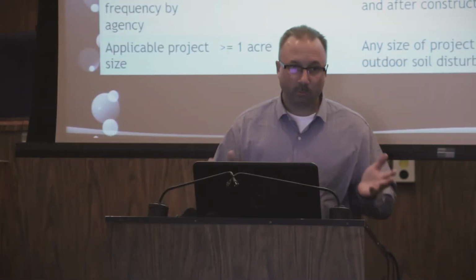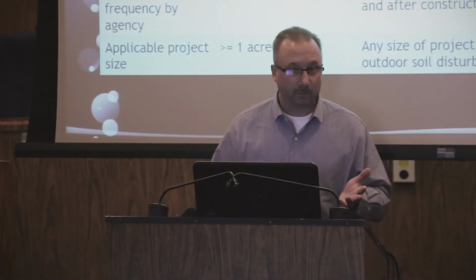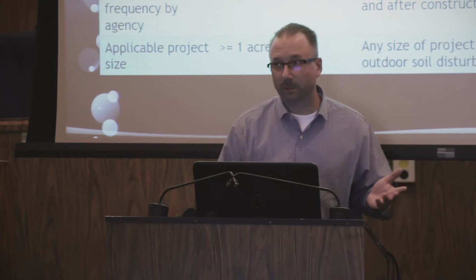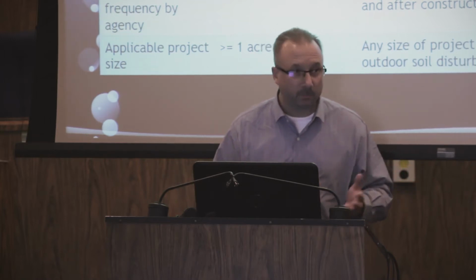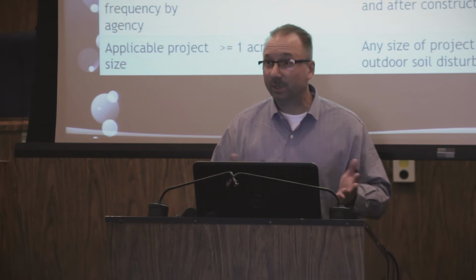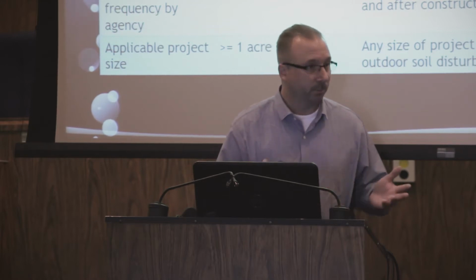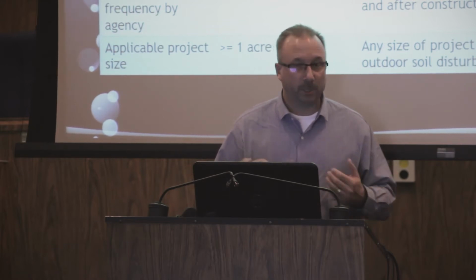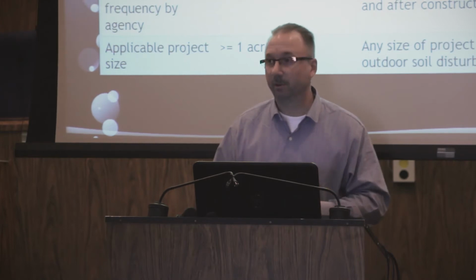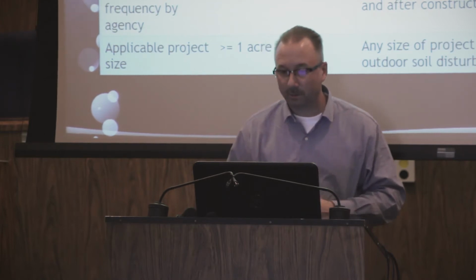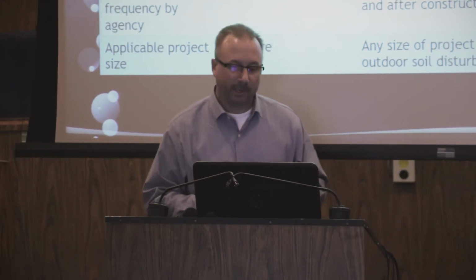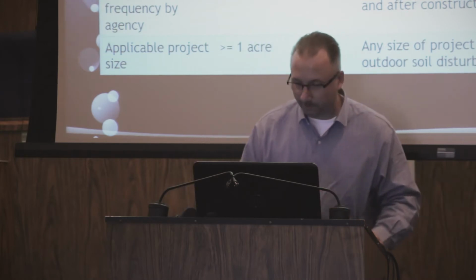And so any project that the city would know about, well, that would be anything that passes through the building permit process, grading permits, plan check, even their own capital improvement projects would need to be on their inventory, would need to have erosion and sediment control plans that we're going to talk about here, and need to be inspected once construction starts, or even before construction.